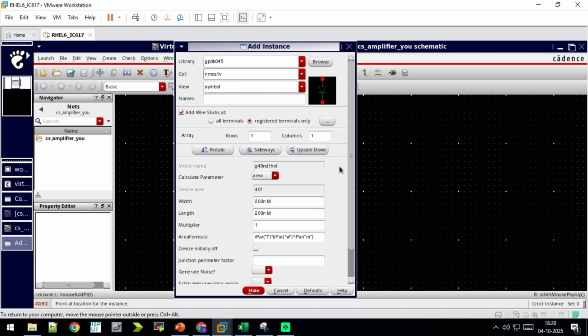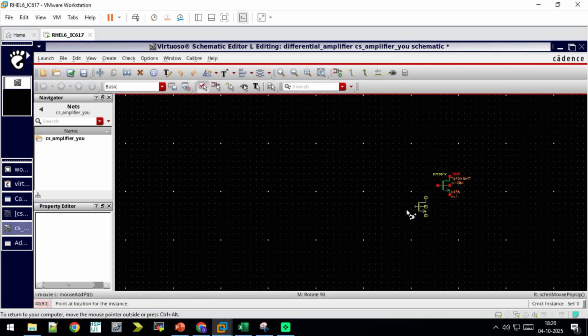1V, and I have to pick the transistor. This is the basic symbol for the MOSFET, and I have to do the configuration. As per the configuration, I have to give input at the gate terminal, and the source terminal should be common for the input as well as output, and for the drain terminal I have to connect a load across which I have to take an output.